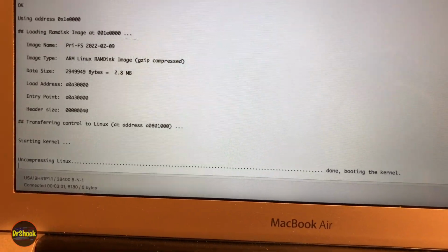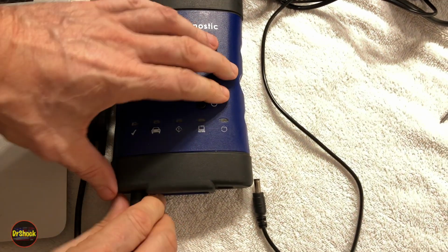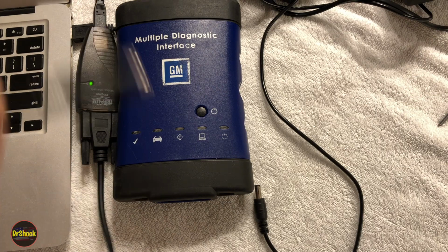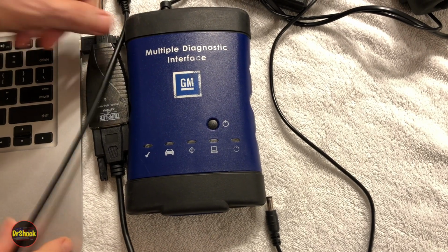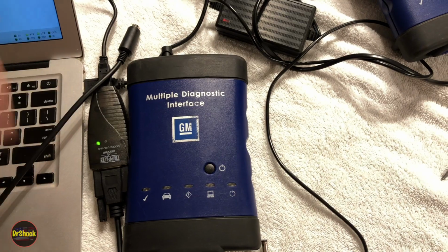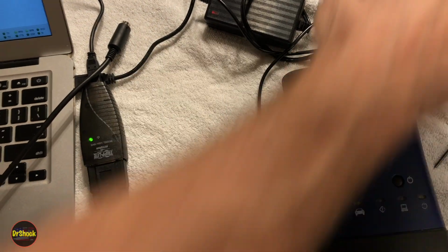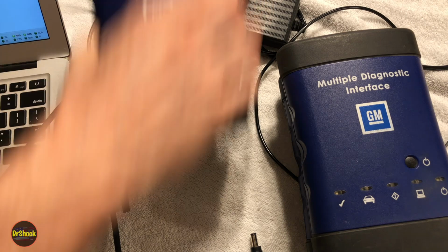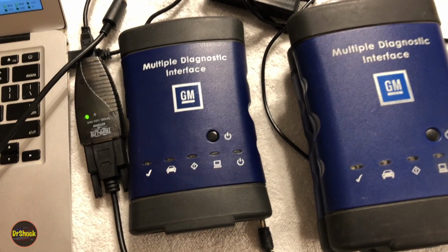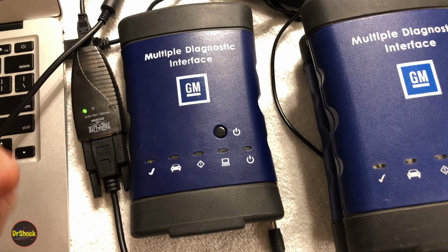All right, so there's the information we've gotten with this tool. So this is a handy tool to help zero in on stuff. You can find all kinds of things like UART errors, post, memory errors, that sort of thing that can help you zero in on what the problem is. At this point, we've got to take them apart and diagnose from there. So we'll start with our first case, and we'll get this guy, the clone, taken apart, and I'll show you through part substitution how we confirm the diagnosis.